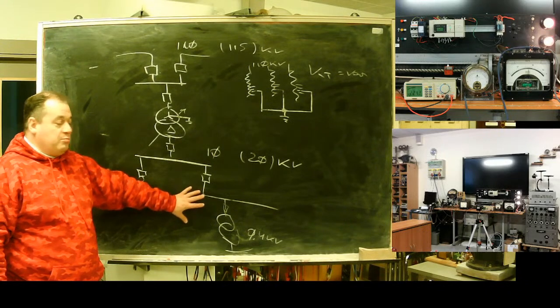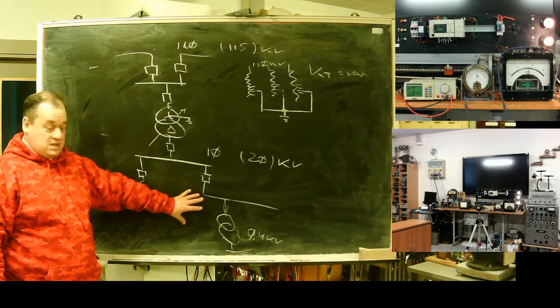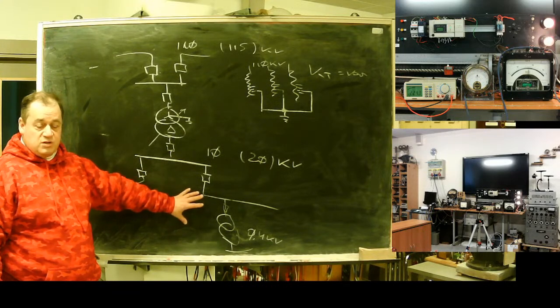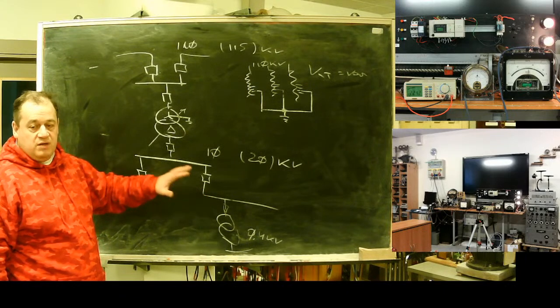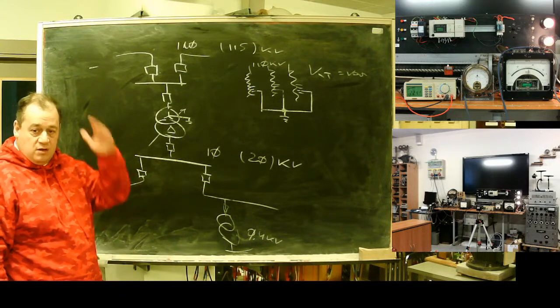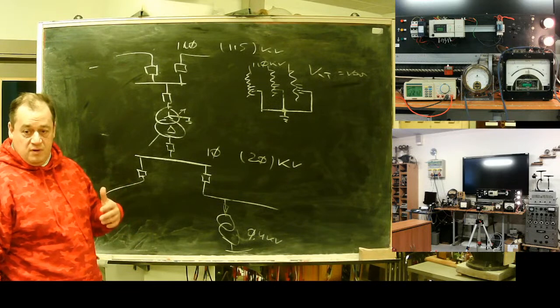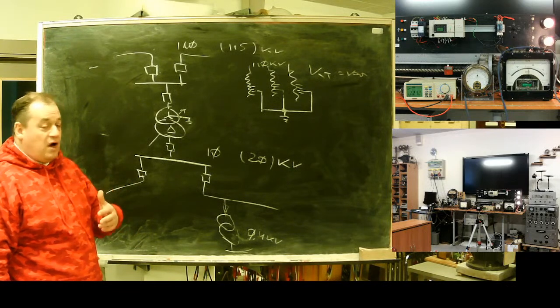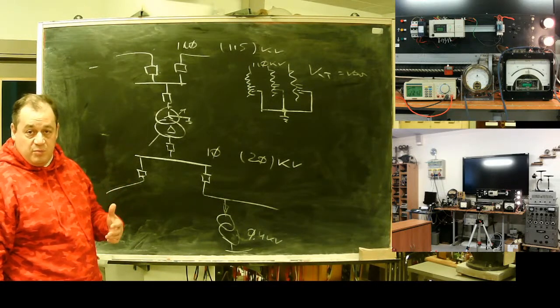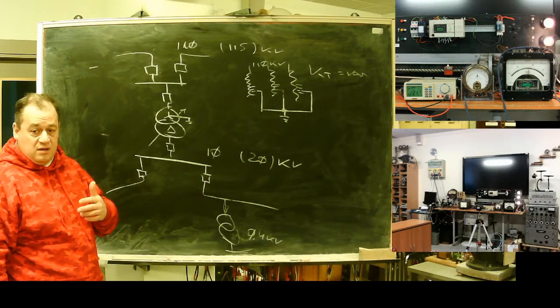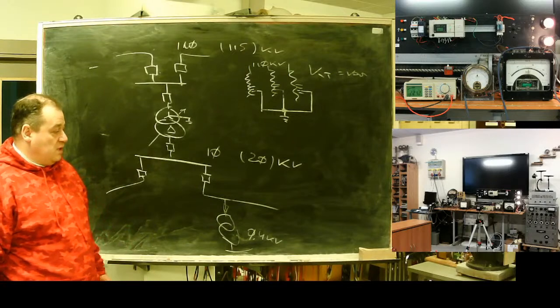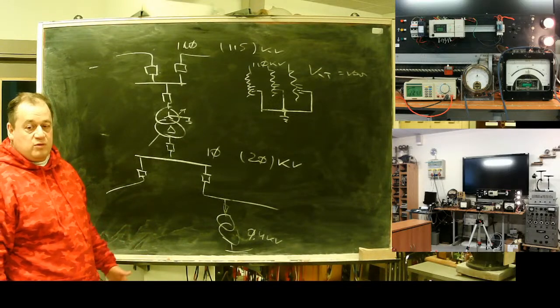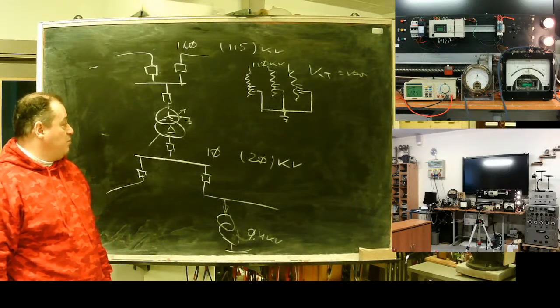It's done because at night there is a serious load decrease, and at morning and evening rush hour we see load surge. If we do nothing, at night there will be overvoltage, and in the daytime voltage will seriously decrease, possibly even making the network unstable.